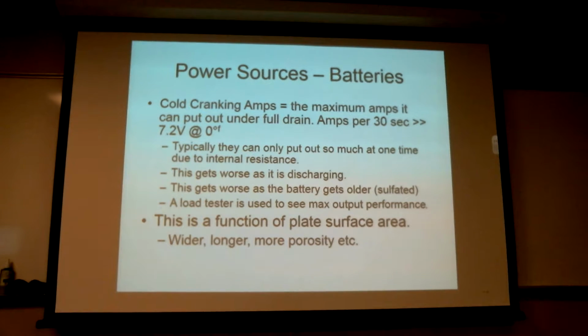And then they may have one or more charging systems, and the charging system will have to appropriately address both of those battery types differently. So you may have a main bus that the charging system is hooked to, and two different charging supplies with different regulators coming off to the battery on that type of complex system. We don't really do that in aviation, because when an airplane lands, what do you do? You get out and go somewhere. Rarely do you pull in and throw out the canopy and the awning and set up shop, or tie it up to the dock and start cooking hot dogs.